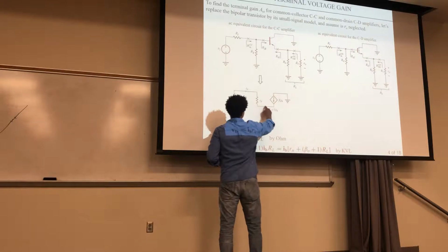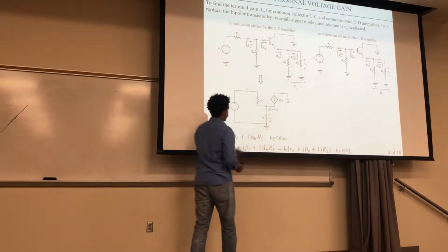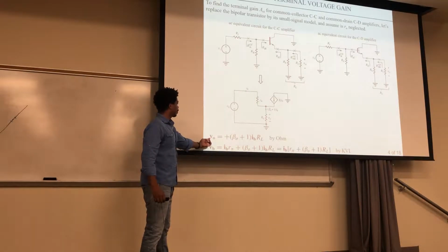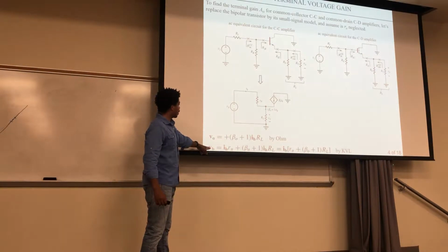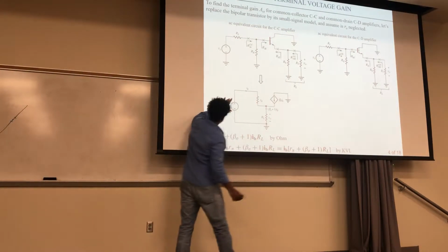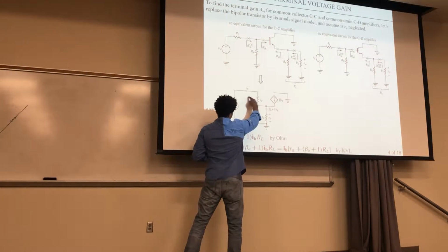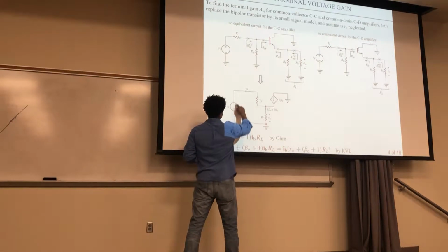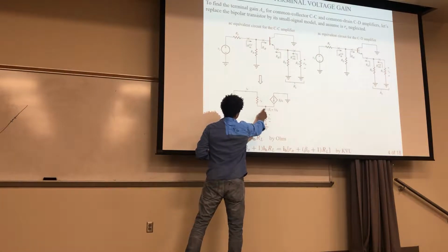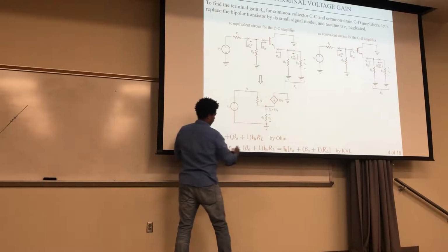This is IB coming in this way, and so this is all the current going through here, right? It's going through this across this load, and so that's the voltage V0. For VB right here, you have this current, right? Here's your VB. You can think of it as KVL going around this loop. So you're going uphill some VB, you're going downhill some R pi IB, and then you're going downhill this amount times RL. So that's what all this is right here.